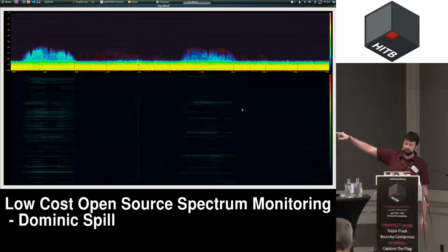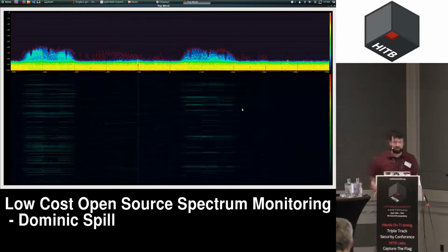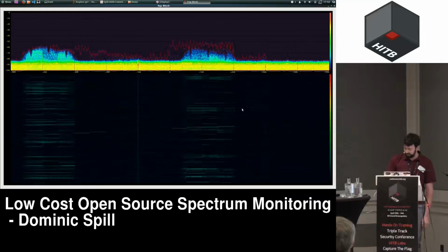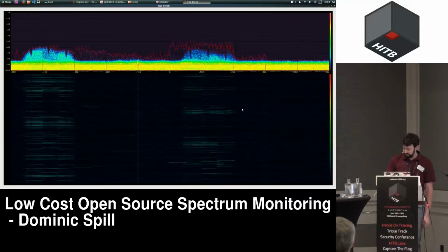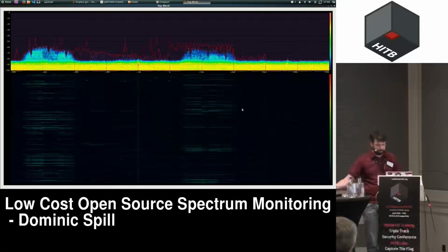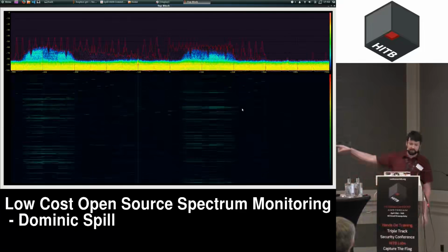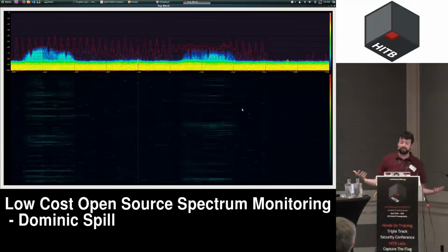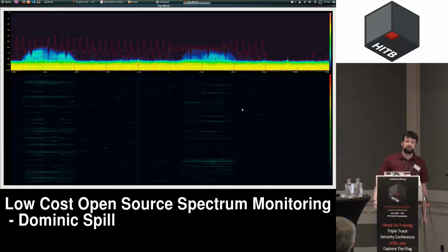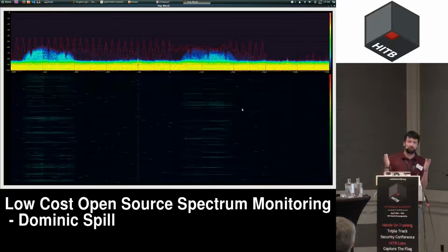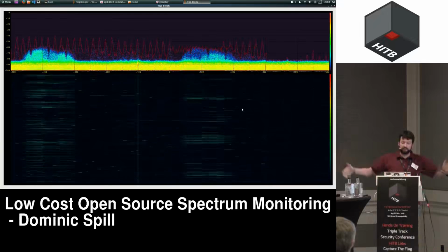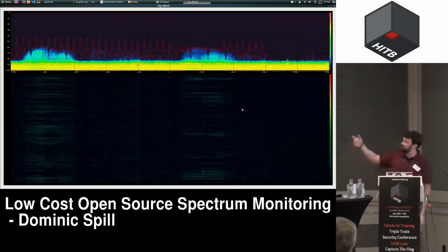So you can see there are 2 large Wi-Fi networks going on. There's a third which is kind of quieter. If I pull out my phone, hopefully I should be able to fire up Bluetooth and have it scan, and you'll see it suddenly spits data all over the spectrum. But the interesting thing here is we're getting the vast majority of that data, as opposed to generally just pointing at a chunk of the 2.4 gigahertz band and seeing what comes in. We're getting these broad packets all over the place. So you can tell quite how much.